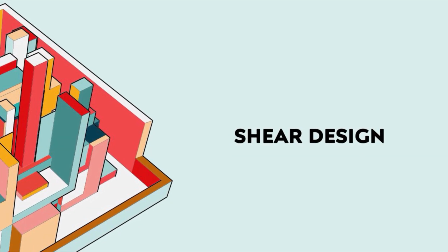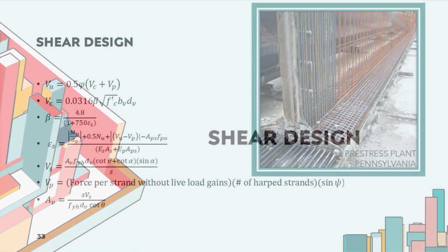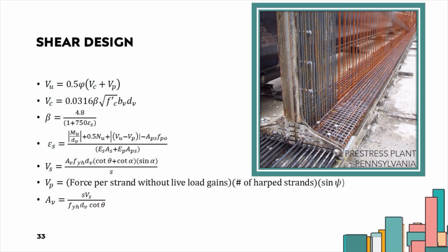The shear design is used to determine the area and spacing for the shear reinforcement. Since the minimum shear occurs at the midspan of the beam and slowly increases to its maximum at each end of the beam, we don't need the same shear reinforcing throughout the entire beam. Using the critical section for the shear, calculated earlier, we can determine the required bar size and spacing needed for the stirrups. The shear design can be broken up into a few sections to determine the different stirrup spacings required for the different shear reactions along the length of the beam.